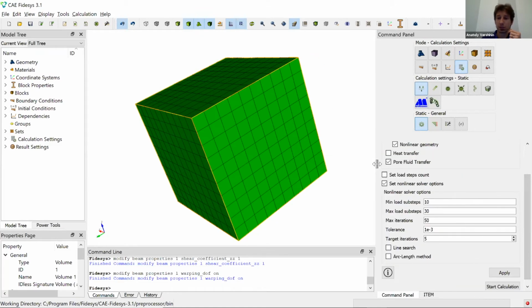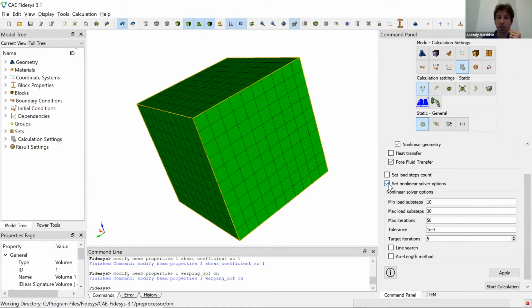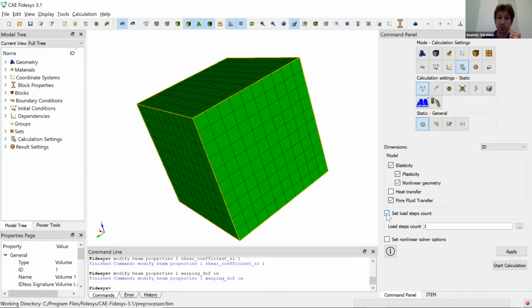One interesting thing I would also draw your attention to is the specification of the number of steps, because the end users, especially in underground mining, introduce boundary conditions not instantaneously all of them, but step by step. Or let's say they originate stress concentrators or remove part of the materials, not in one step, but again in several stages. Or like in 3D printing, when we print layer after layer. So it's again multi-stage loading.